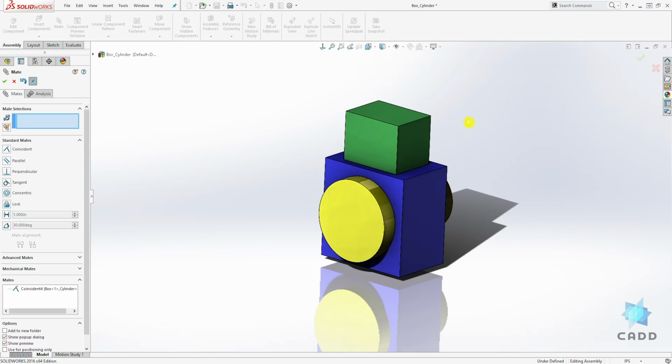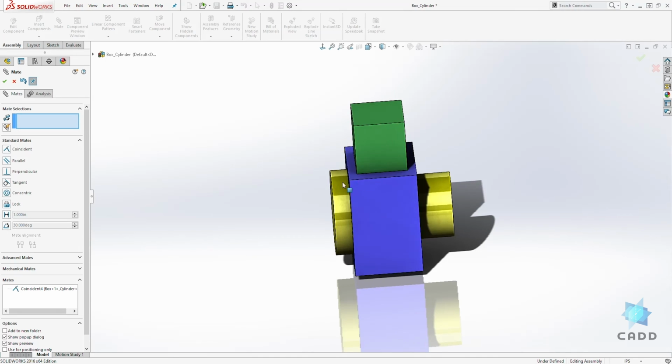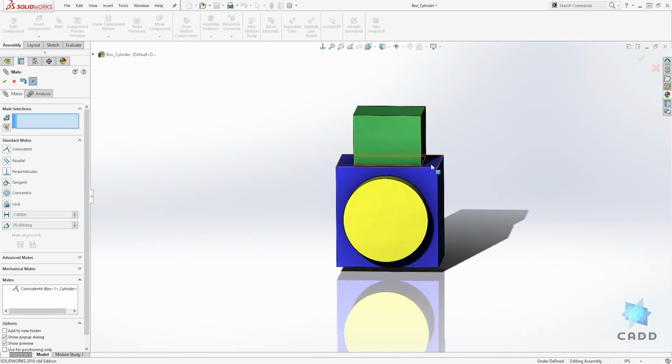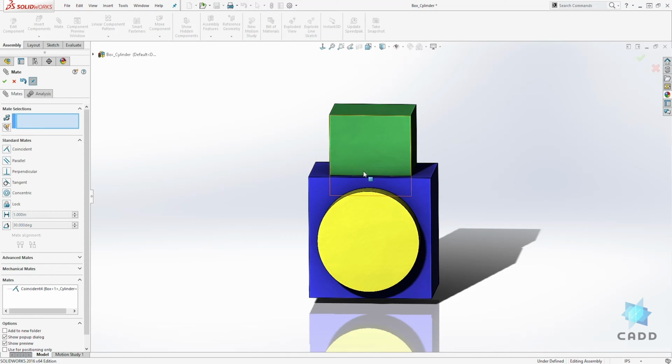So that is the basics of SolidWorks mates, and you have all these different standard mates. The first one is coincident, the other ones are parallel, perpendicular, tangent, and concentric. You'll be using these standard mates based on the part you are working on and the type of mate you are trying to achieve. So that is the basics of the mate. Remember, you always need to lock it in 3 ways along the X, Y, and Z. So let's move on to the valve body.